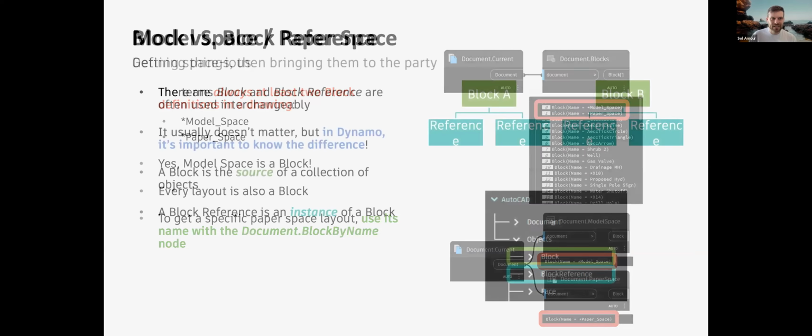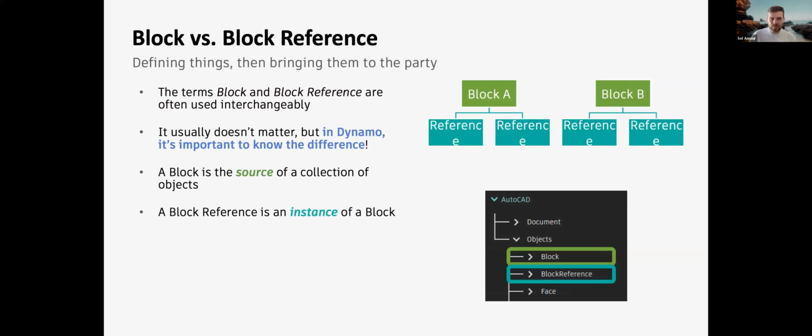Awesome, thanks, Zach. So moving forward a little bit to blocks and block references. Apologies for the spelling. It looks like my font size jumped around a little bit here, but you can see that is actually block and block references essentially. The terms block and block reference here can be used often interchangeably, but as Zach mentioned earlier, you can think of a block as a container of things, and then a block reference is a reference to that container. Essentially, what we're doing here is we're defining something, and then we're bringing them to the party. And we can bring lots of them to the party if we want to have a loud one.